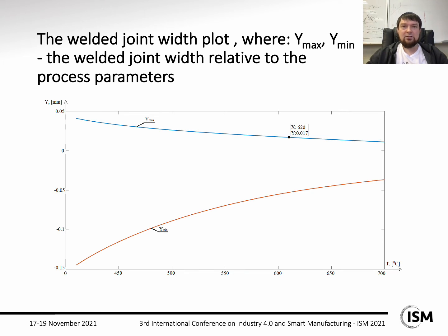At this stage along the way, we calculate the heating zone limited width, which is the welded joint width equivalent. This parameter can be used to predict the seam width in case of changes in the welding technological modes, such as welding speed, welding current, changing focal length.